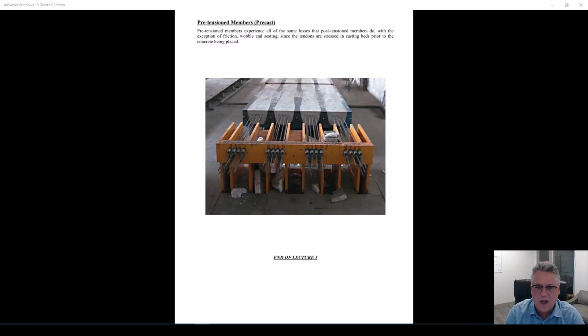It's going to be the only time where you are actually using less of something to solve a problem. So in post-tension concrete, we are thinking in terms of less cowbell, while the rest of the engineering world thinks more cowbell. If your shear is not working, you need more area. If your bending stress or your flexural strength isn't working, more section modulus, plastic section modulus, elastic section modulus.